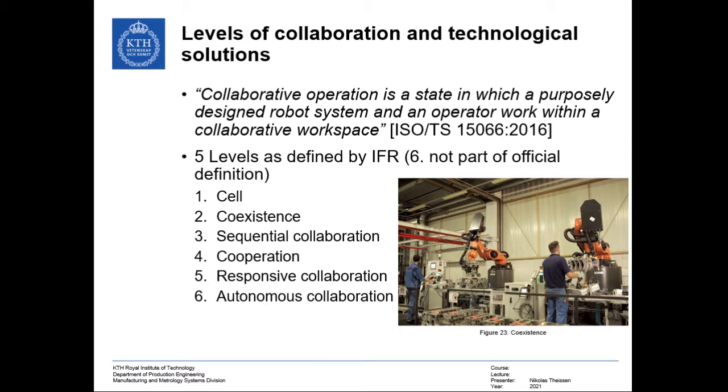The presence detectors that are most commonly used in robotic safety are pressure mats and light curtains. Floor mats, also called pressure-sensitive mats, light curtains, which are similar to an array of photocells, and laser scanners, can be used to detect a person stepping into a hazardous area near a robot. Effective presence sensing devices stop all motion in the robot if any part of a worker's body enters the protected zone.